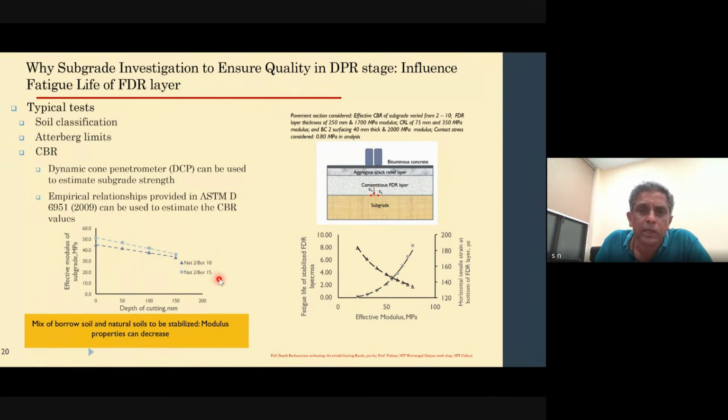Now, if I take that in a larger estimate, the quantity that requires to go into a truck, the easiest way to do that, which is how it is being done in the field. You have a 4,000 liter truck that you're using. Now, the requirement is 0.01 kilogram per liter multiplied by the total volume of water, which is 4,000 liters. So if I have a 4,000 liter truck, I need to add 40 kilograms of my liquid additive so that I can distribute that 2% quantity of additives into the entire depth of my FDR material. So that is how you estimate the proportioning of the liquid additive that needs to be there.